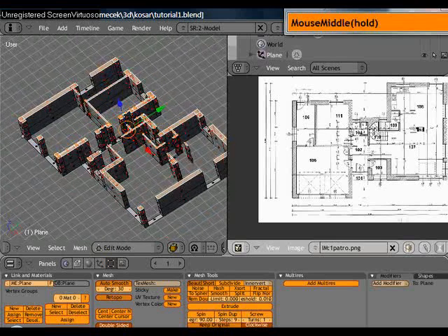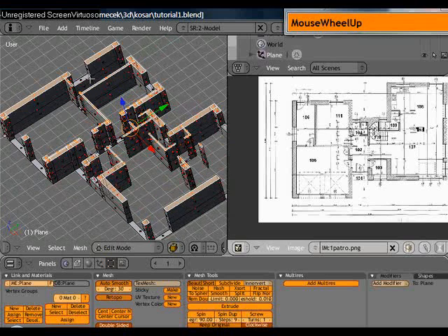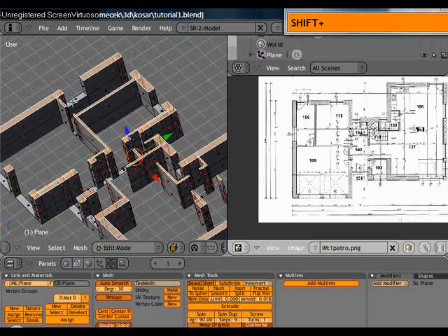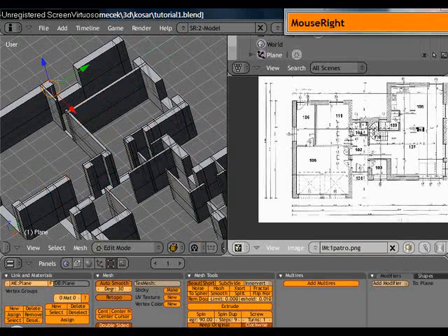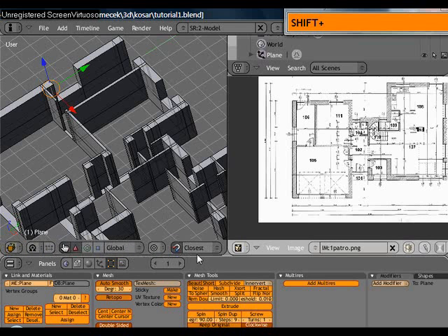Now I need to close the windows and doors on the top part, because I'll be extruding solid wall. So what I can do, I can Control Tab to go to edge select mode, and I can select those two edges here. Now I selected the back of the object, so it's easier if I do that, to come over here and press this button to limit selection to visible, so it wouldn't happen anymore.